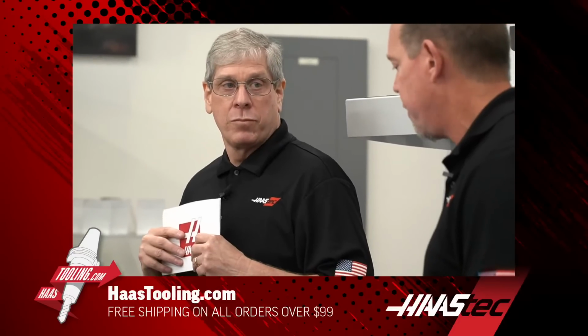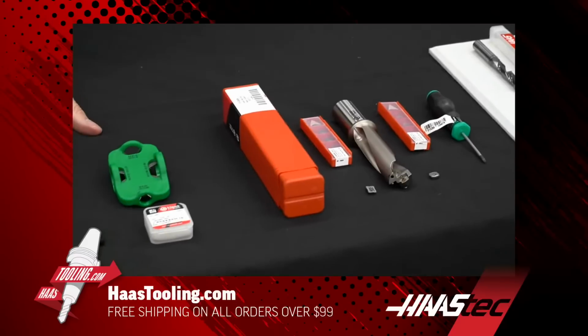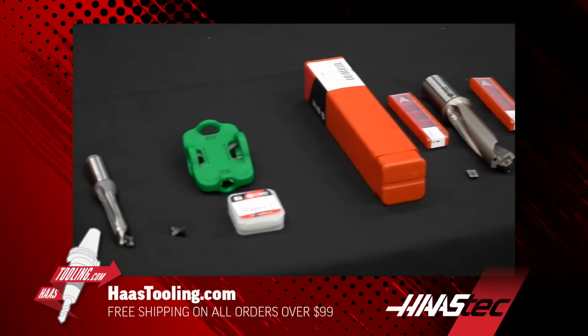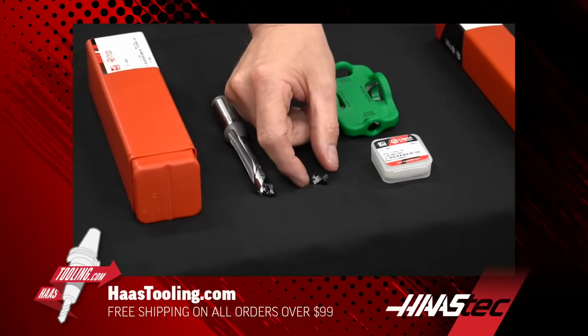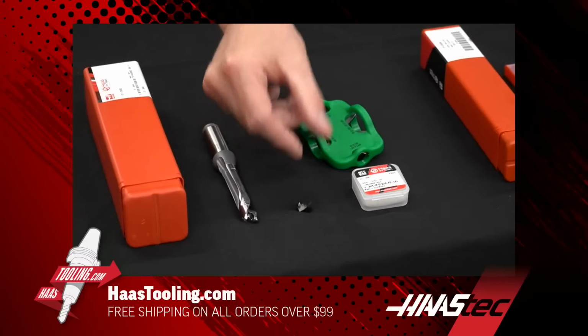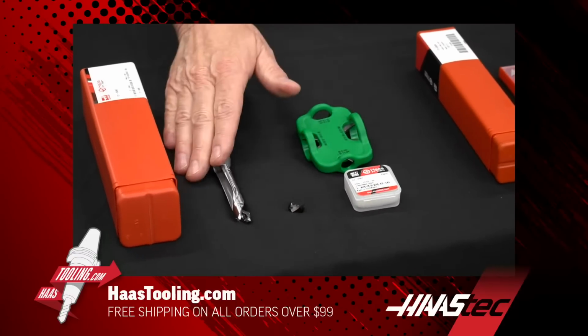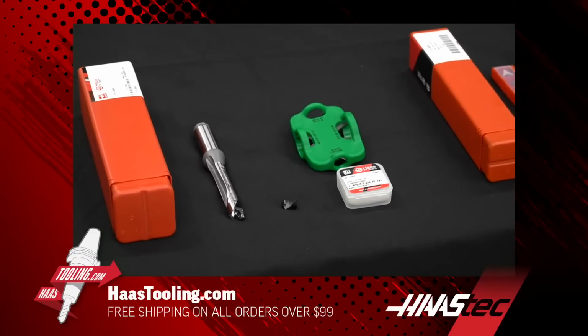Okay, so let's get started here. We're going to start with modular and insert drills. Yeah. So here's the modular drill. This is an example of one of them. These are tool steel bodies that take a carbide insert that goes in the tip, and here's the tool that comes with the body to install the inserts. And essentially these are for your medium-sized holes.